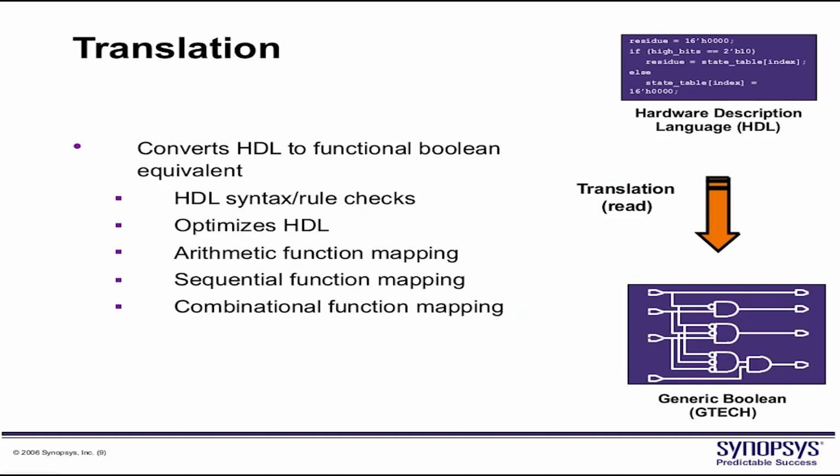So the process of translation we now see in detail. It will cover all these things. It will do HDL syntax and rule check. It will optimize HDL. We'll see a few reports. It will map arithmetic functions.